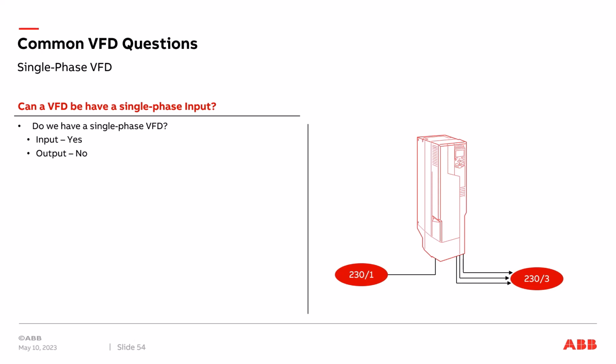Now be careful. People will suddenly ask you, saying, I have a 3-phase 230 volt air handling unit. I want to use your drive to support the whole air handling unit. The first thing you need to ask is, do you mean the motor in the air handling unit, or do you mean the whole entire air handling unit? The drive is not a power conversion device. You do not want to plug it into a full air handling unit. You'll have many other issues.